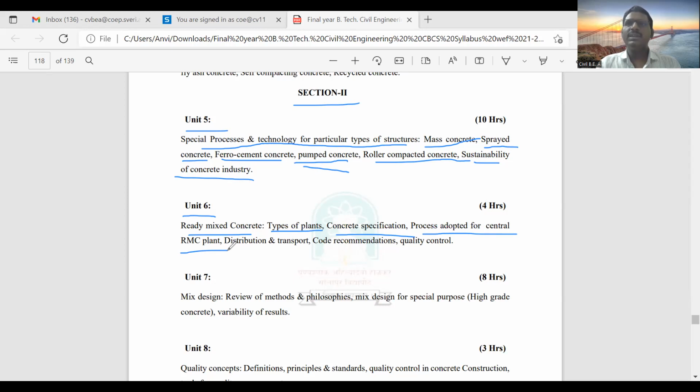Then we have to give the requirement of sand. If 700 kg of sand is required for 1 meter cube, then 1200 kg of aggregates are required for 1 meter cube. Automatically, the 1200 kg aggregate, 700 kg sand, and 8 bags of cement are lifted from the units. The automatic RMC plant also handles the water requirement automatically. Nowadays we only have to give the input to the computer, and through the online automatic system we take the sand, cement, and aggregate and mix them in the mixer in the RMC plant. Nowadays every taluka level city also has RMC plants.